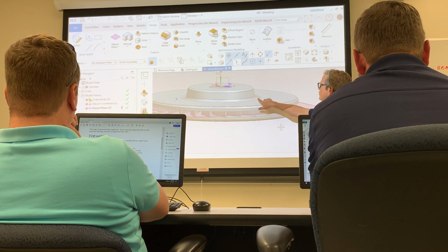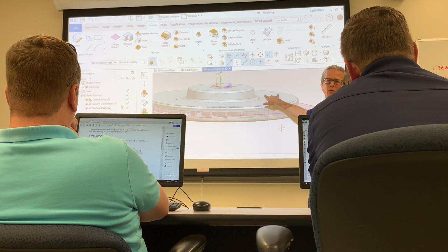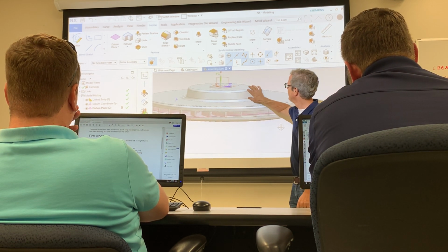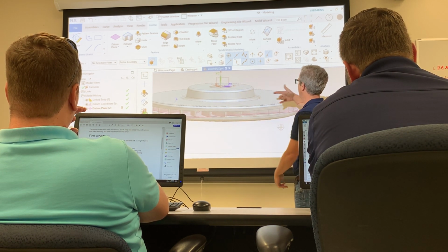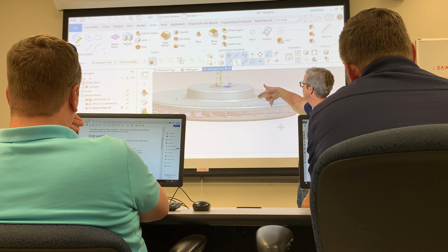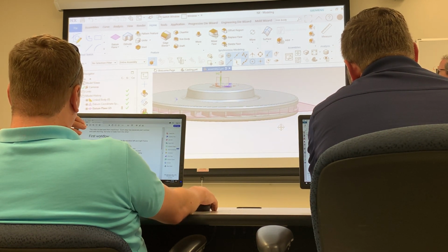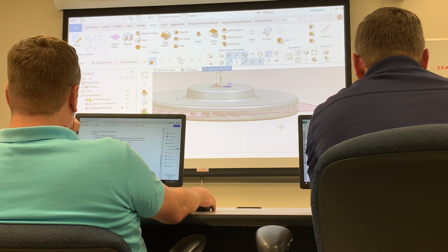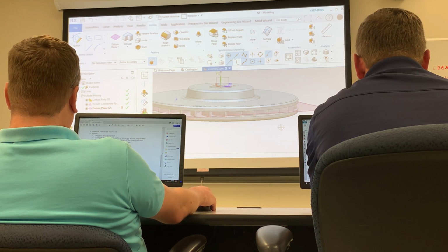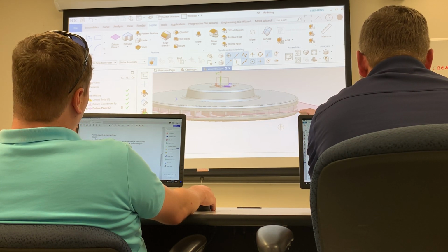So you'd have to have like a donut-shaped circle sketch to trim this, because you'd want to be able to trim this without trimming anything in here. So that means you'd have an inner boundary and an outer boundary, and you could use that one donut-shaped sketch to move that away. The only problem with that is, and it's not really a big problem, you'd have to think about what would be your start distance and your end distance.